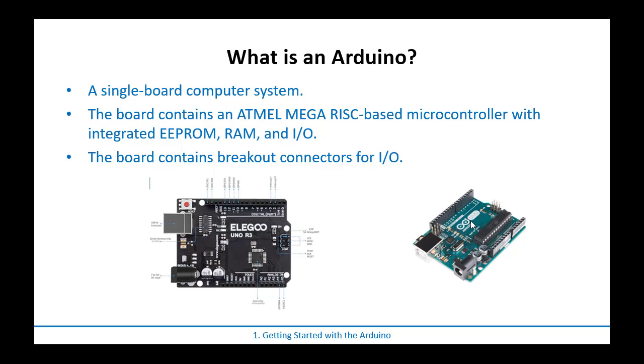This is how you mount all integrated circuits to talk to each other. So motherboards and the boards in your phones. And so this is a single board computer. What that means is that on one board, you have everything you need for a computer. That's the central processing unit, which understands how to execute all the instructions that you give it, memory to hold the instructions for the software you're going to write, memory to hold variables that you'll use temporarily during a program, and then also inputs and outputs. So little pins where you can drive LEDs, read from voltage sources, or drive motors.